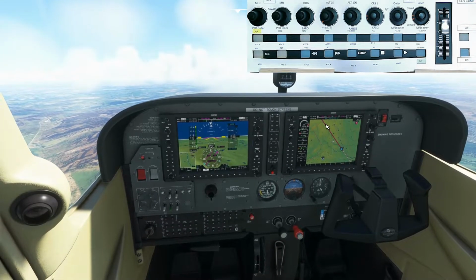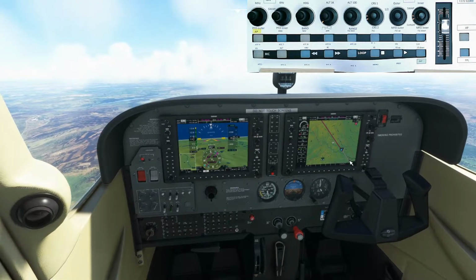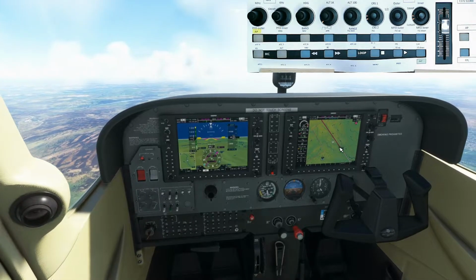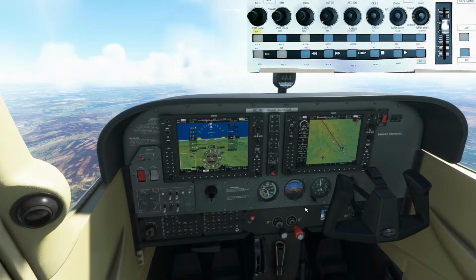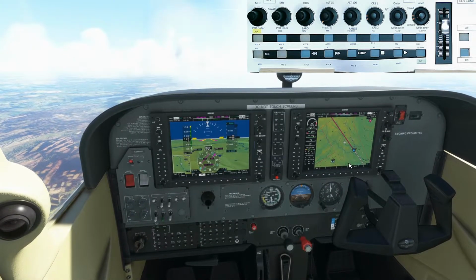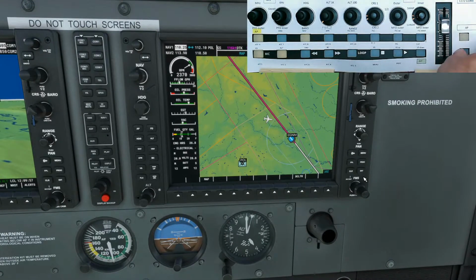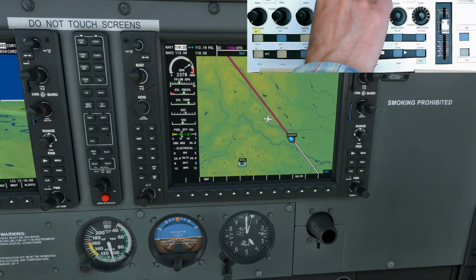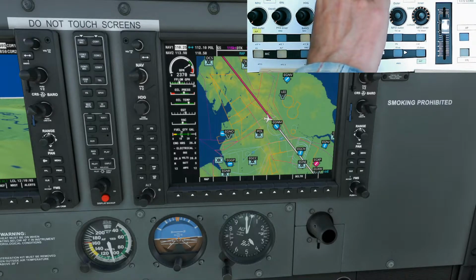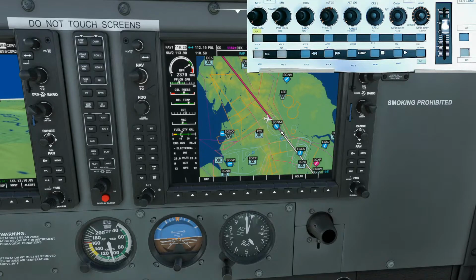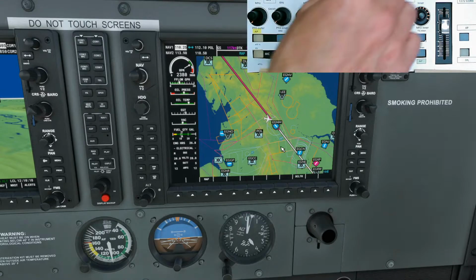And you can see that that carries on past the point. So we've still got the track following out, so we can follow that out. If we look at the range here, that takes us pretty close to where we want to be. But what I'll do is, as I come over the point here, I'll put it onto heading mode for a while, and then flick it back onto the proper GPS that we've got, the flight plan we've got programmed in.